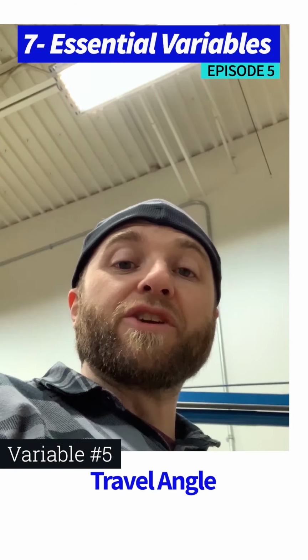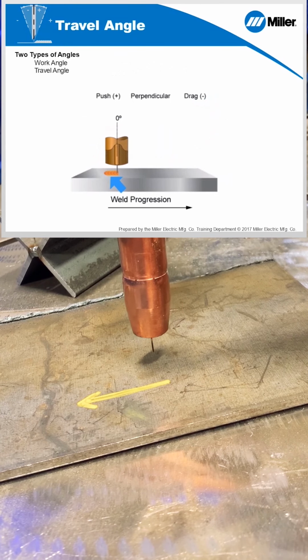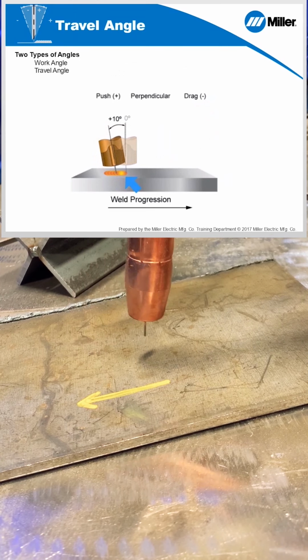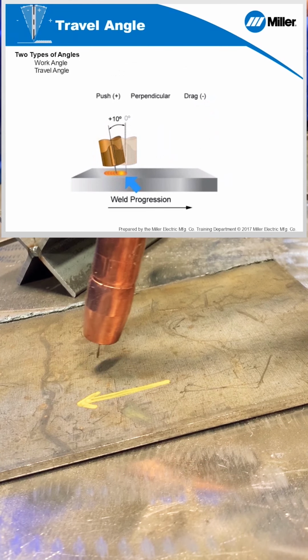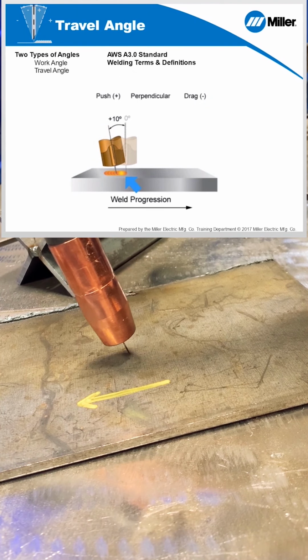Number 5 on the list is going to be travel angle. Now let's talk about travel angle. Travel angle relates to the direction of travel. Then I'm going to produce an angle of some type, whether it be a 0 angle in some cases. I might need a 10 to 15 degree push, which is very common. Depending on the electrode, it could also be a drag case.